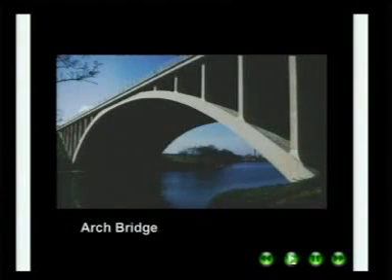Yeah, next one. What you see here is what is called an arch bridge, and these are called the spandrels. You need a straight road, the car cannot travel like this. So you create an arch as a structural member which transfers the load, then you have the spandrel members on both sides, then you have what is called the decking. On the decking you have the road surface, and beautifully you go. There are beautiful arches in California, in Switzerland.